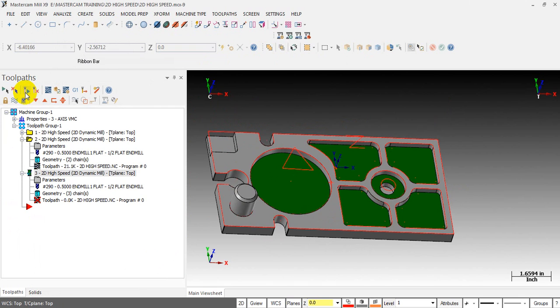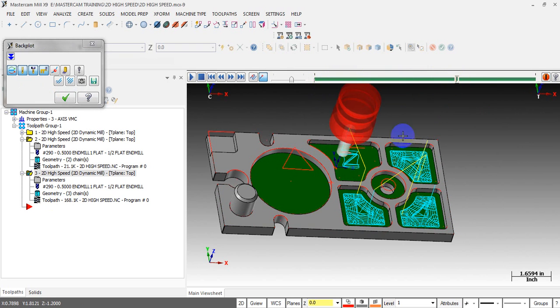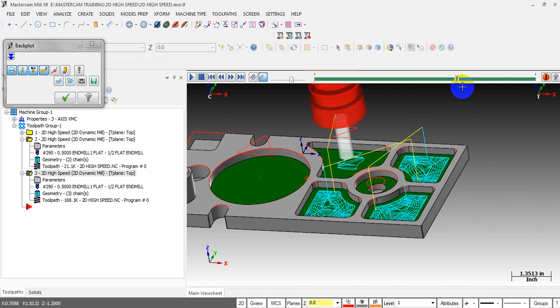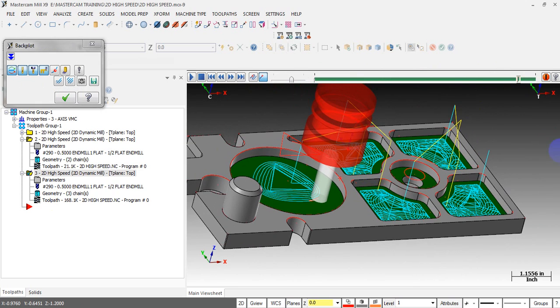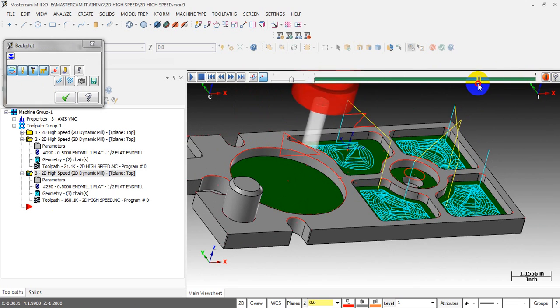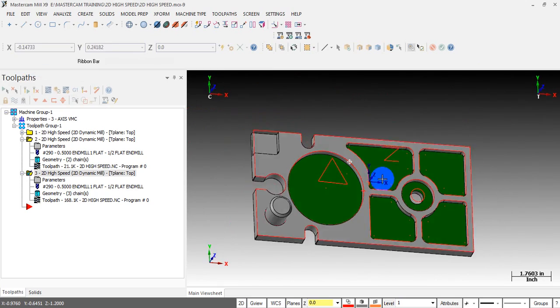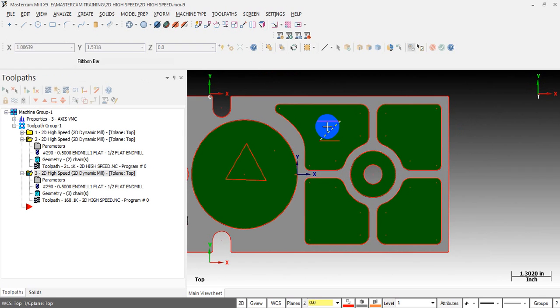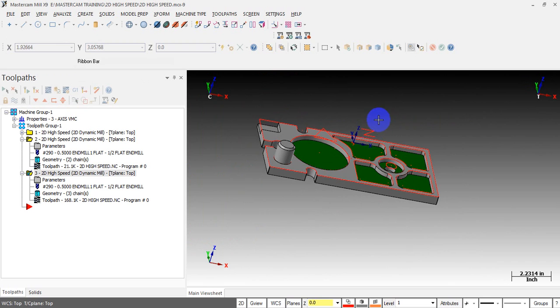We generate a toolpath. So let me see. Okay, a Z style entry motion in this pocket and a triangle style motion on this pocket. So Mastercam is very intelligent. It will check that this entry motion is the custom chain used for this pocket and the triangle style chain is used for this pocket. Yes, that's what I want to show you.